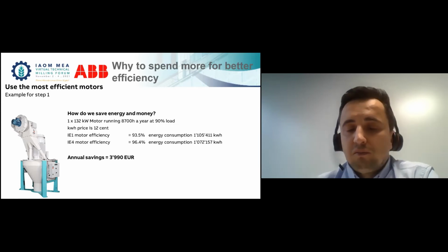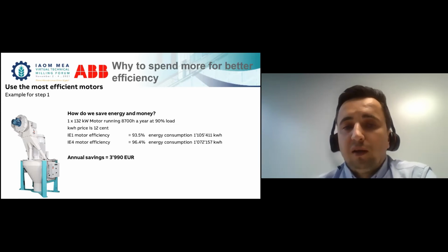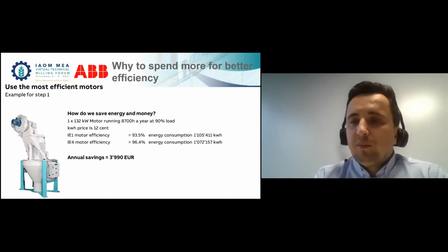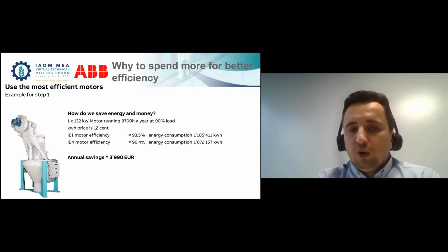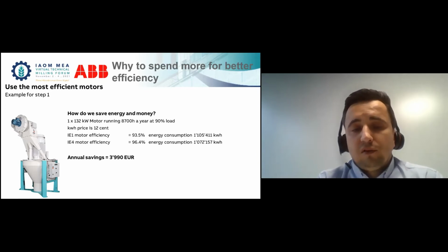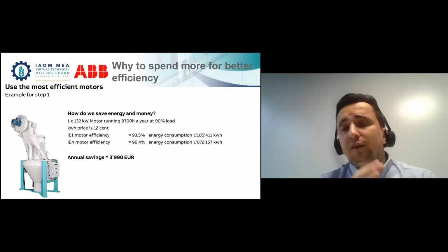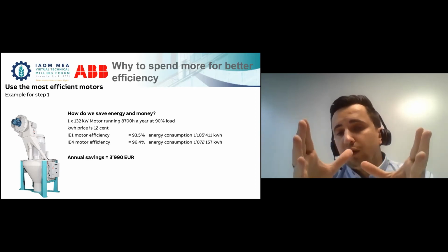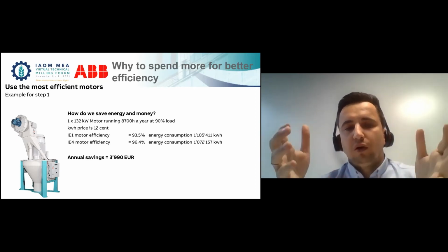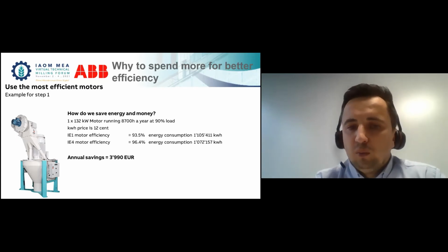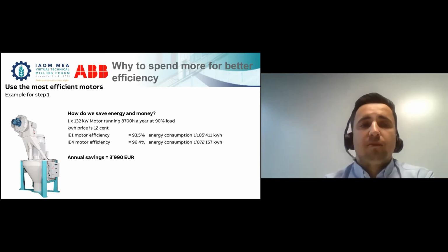So the return on investment is quite fast. If you compare, you have to spend a certain amount for an IE1 motor. It's, as an example, 10,000 euros or dollars, and the IE4 motor is 20 or 30% more expensive. Then this 20 or 30% which you are spending more for the more efficient motor is returned in a very, very short period of time, in 1 or 2 years.